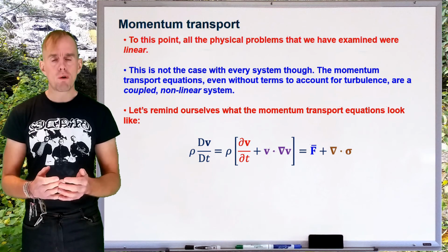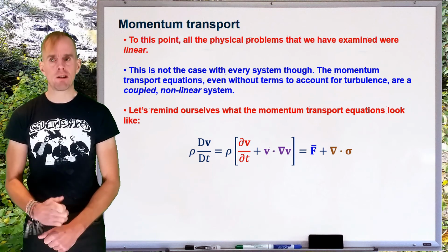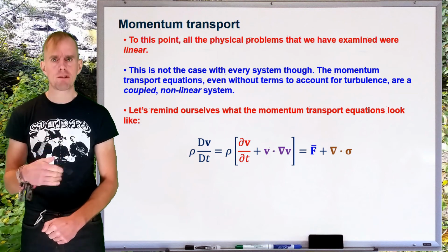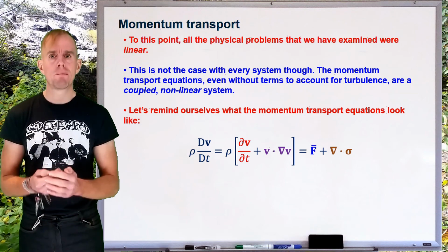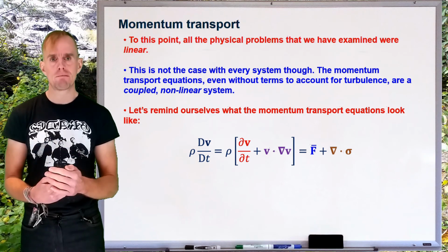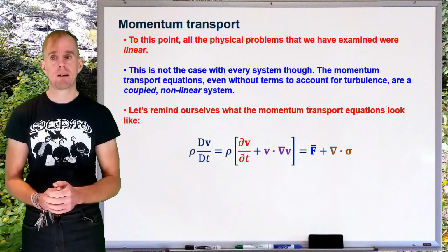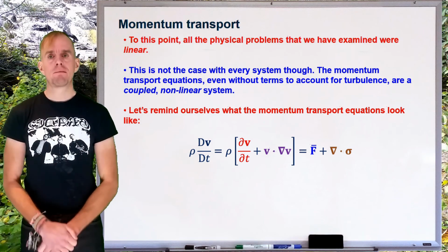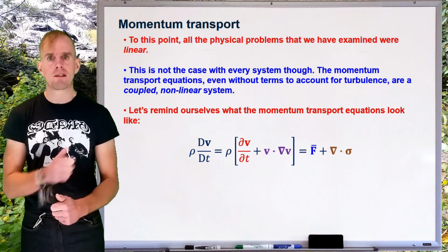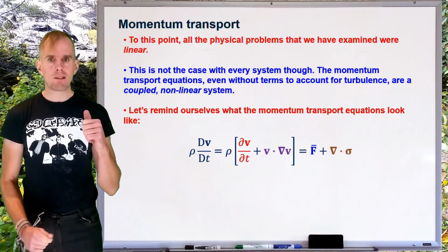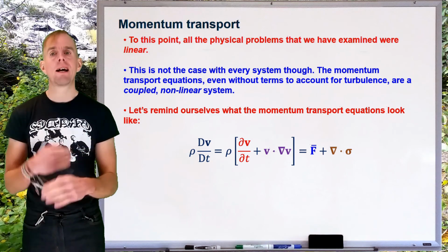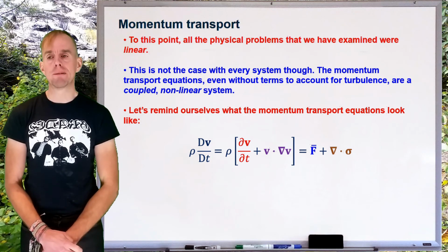Now let's just draw back from the maths a second and convince ourselves that what we're looking at is actually momentum transport, and let's also recognise what form momentum comes in here. Is it just momentum, or is it scaled by another quantity? So, recognising that every equation has to obey dimensional homogeneity, that is to say that all the additive terms take the same dimensions, let's take the simplest term here, which I'm going to take on the left hand side, rho dv by dt, and examine what fundamental dimensions describe it.